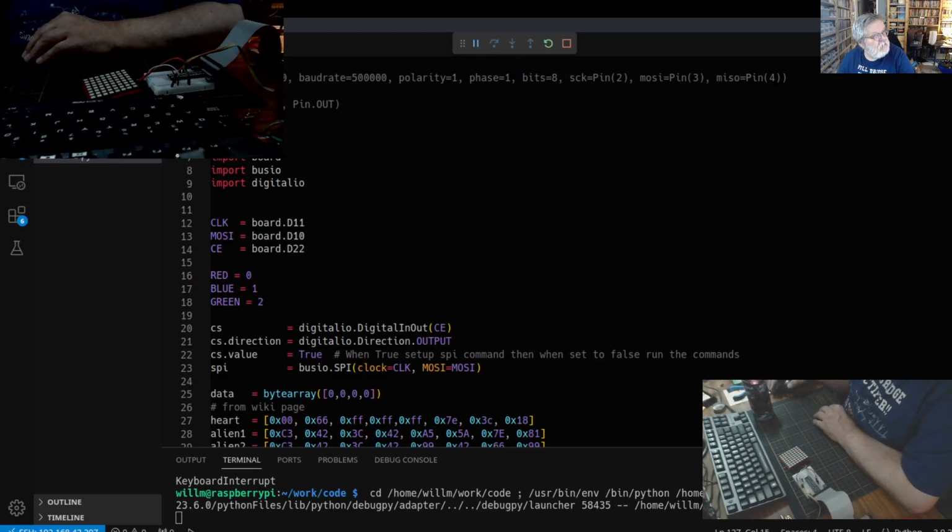Where did I have that? It's also in like the demo code for Adafruit. It's right in the block of messaging code at the top telling you how to set up SPI. But you have to be careful. There's only, as I said, 4 pins that are technically valid for doing this on a Raspberry Pi. Okay.